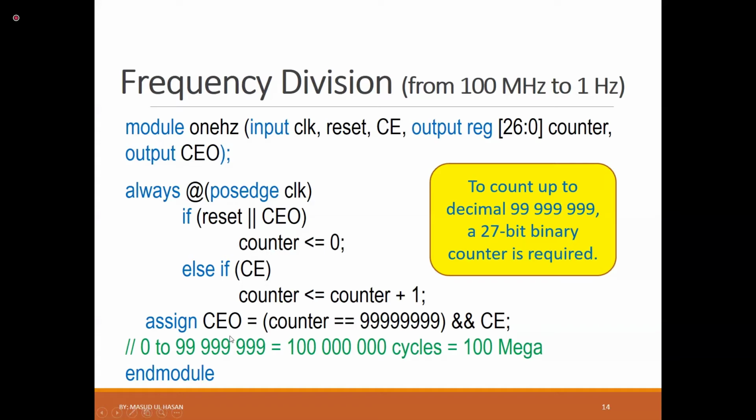Okay, now this is the main code. You have to change it to yours. Like here I have mod 10, mod 10, mod 10, mod 10. You have to make it mod 10, mod 6, mod 10, mod 6. Understand? And the rest will be almost the same.